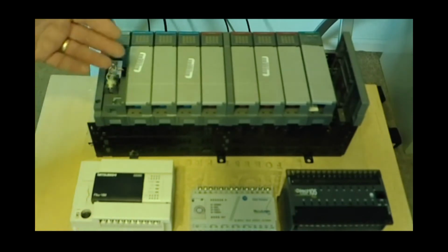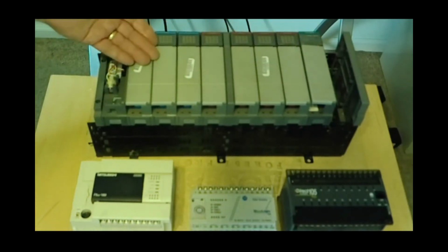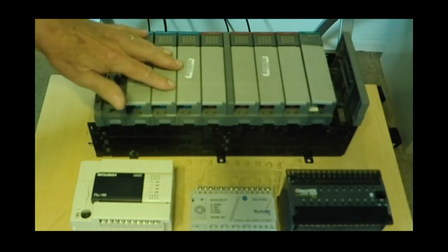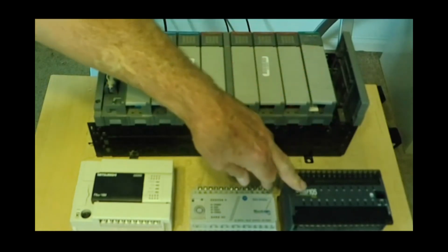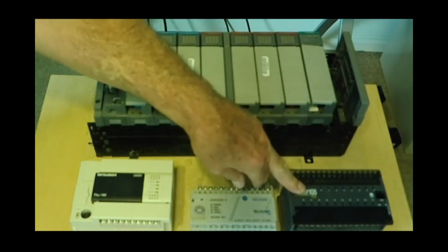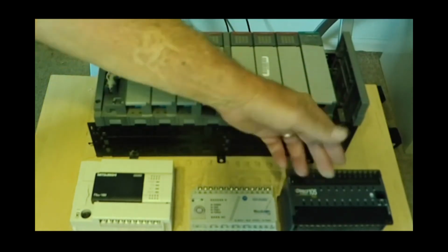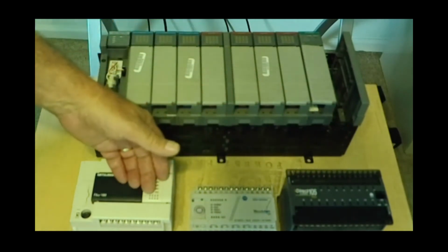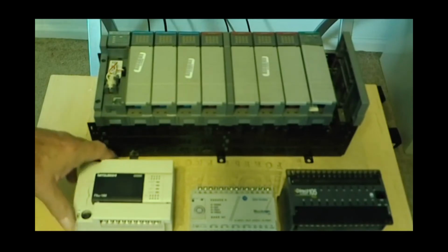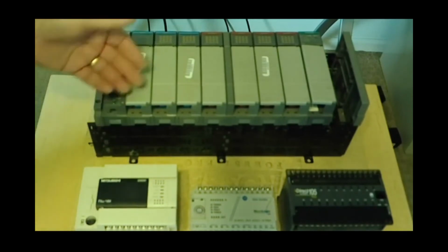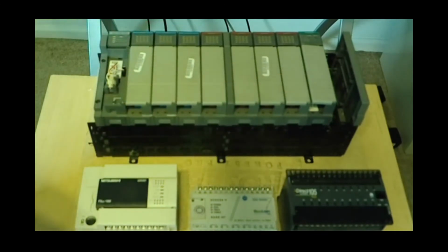Well, the question is now, how many terminals do you need? If you need a lot of inputs and outputs, you go with a rack system. If you're just operating a simple air handler unit or maybe a small boiler or small equipment, a brick PLC is nice. If you need high-speed switching, then you go with the Japanese brands. But these are all workhorses, and I'm not going to put one brand in front of the other because every one of these guys do the same thing, and every one of these are going to work fine.